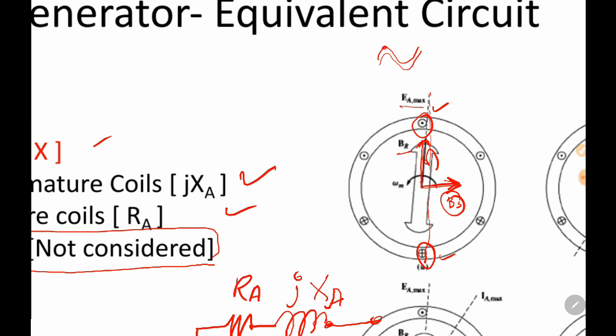it will induce an EMF into the coils, because of course it's also rotating. Think about it: you have two vectors connected end to end, and those are rotating now. So this vector will also be inducing voltage. If you see the terminal voltage, which let's represent by V phase, that will be equal to the EA voltage, which was the voltage produced only due to the rotor magnetic field, plus the E stator voltage.